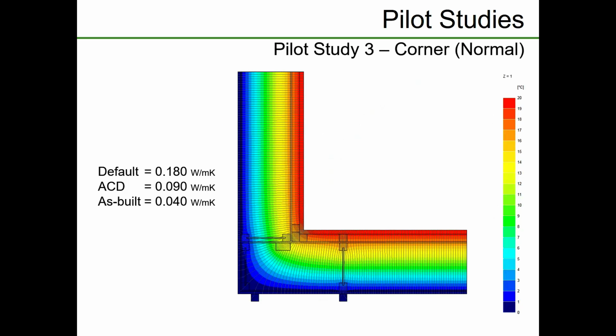This one is a Passive House project, 300mm of insulation in timber stud. These were cassette panels, so they came to site ready built, and then they just connected the panels together using a very clever cam system. And it had sheathing board internally and externally, and then it had a second sheathing board over the top of the structural sheathing board. And it was a Steico or similar, which has a low conductivity. So essentially what it's doing is trying to reduce the thermal bridging through those I-studs. As a connection detail of those panels, very, very good.